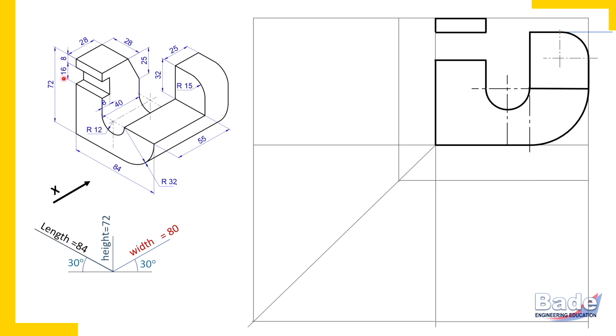Watch here, it's given 16 millimeter here, and length 28 millimeters. This length is 28 millimeters. Watch here, these edges are 28 millimeters long. So this surface is partially hidden, but from front it is completely visible. It has principal edges of 28 millimeters, which we have already drawn. Then 16 millimeters vertical, one on this side and one on the other side. So those two edges, this is how we have completed that surface.